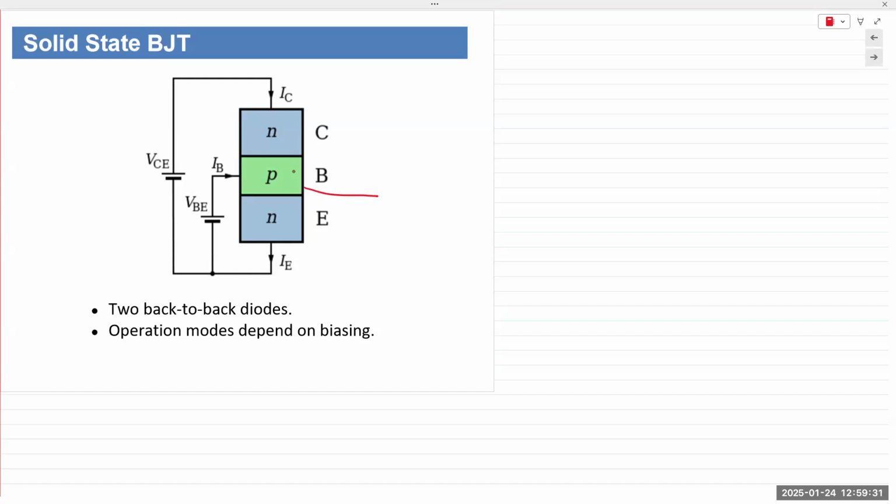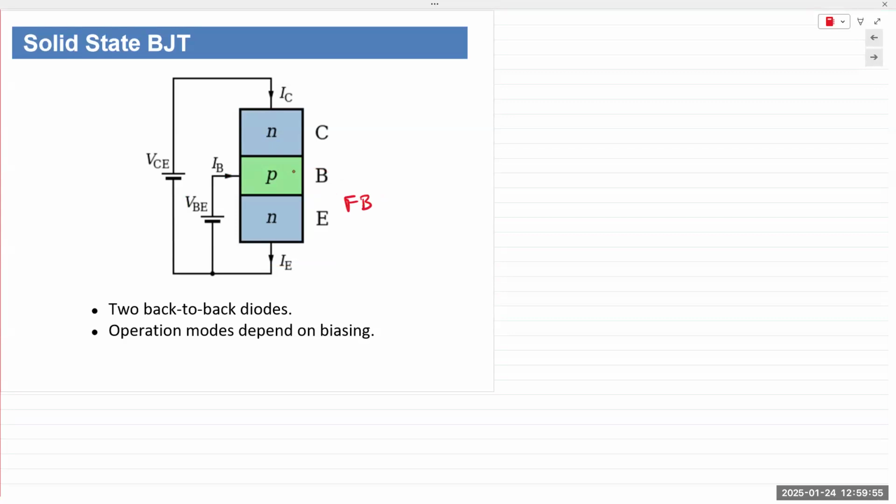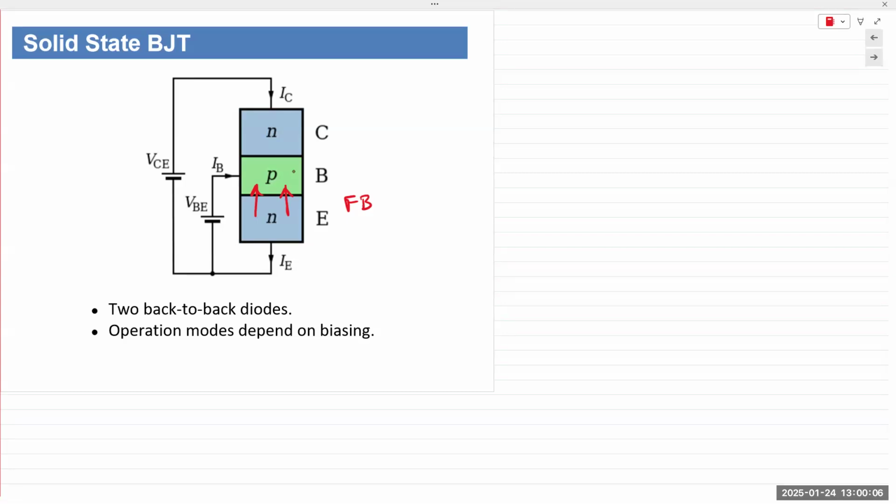And there's a few other illustrations, but I just wanted to cover at least this portion. It's basically the emitter base junction behaves like a true diode. So you forward bias the base emitter junction, which is right here. You apply a positive voltage to the base, negative to the emitter. Forward bias. So a large number of electrons in the emitter material cross over into the base. But because the base is very thin and is the most lightly doped of the 3, there are not enough holes available in the p-type material to recombine with the electrons. So many of the electrons are like, what do we do now?